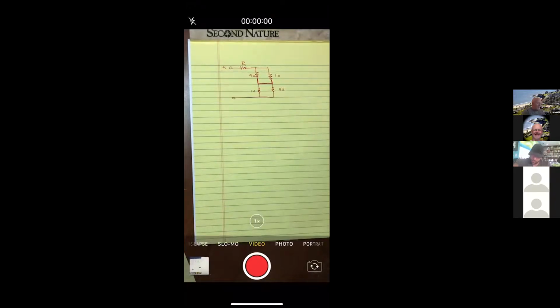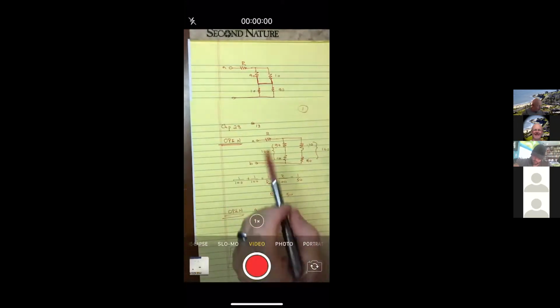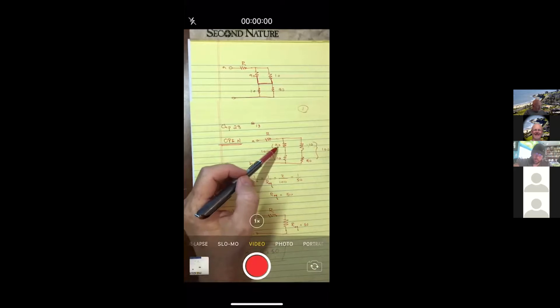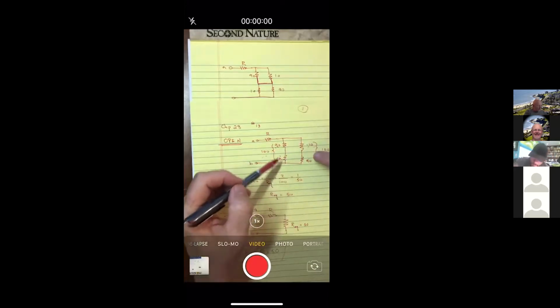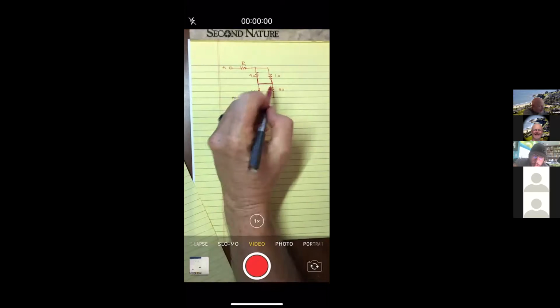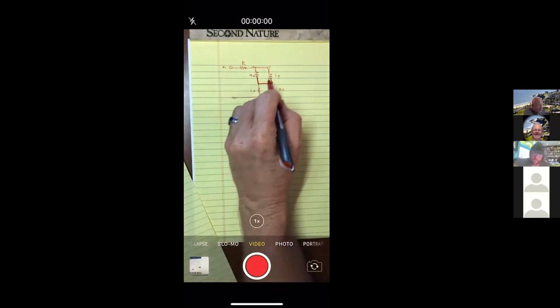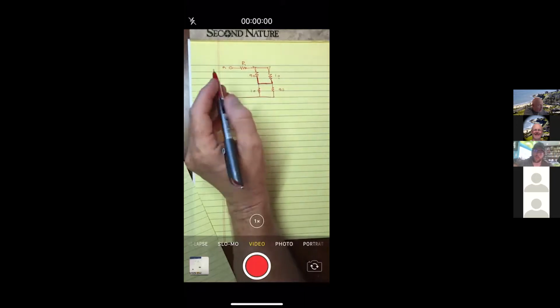All right, so I'm going to do the same thing, but here's where it differs. Back here, this 90 and this 10 were in series, so I put them in series first. Then the two collectively were in parallel. But what I'm going to have here, once I've connected them, is the 90 and this 10, not this one, are in parallel.